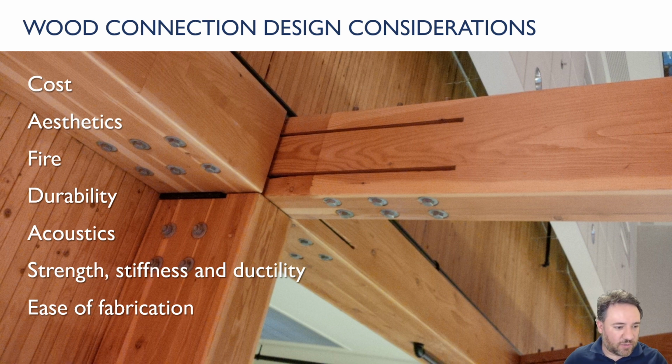Okay, so there's a lot of things that we might want to consider when we are designing connections in wood. And the thing about wood connections is they often end up being the weakest component of the timber structure, because a lot of the ways that we connect wood engage some of the brittle failure mechanisms that we talked about when we talked about wood strength and mechanics in general. So designing timber connections that have really high strengths can be a challenge, and we'll see in this lecture some of the options for designing connections that have larger strengths than maybe conventional connections do.